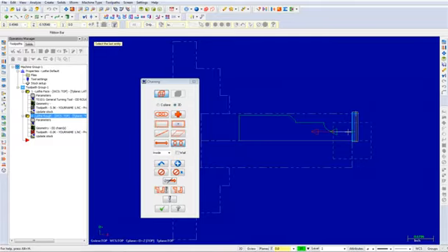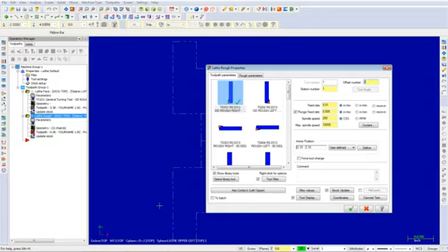Make sure that the chaining direction is set to counterclockwise. Otherwise, select the Reverse button in the chaining dialog box. Now select Entity B as shown and select the OK button to exit the chaining dialog box. From the tool list, select the same tool from the previous operation and input the comment "Rough the part."